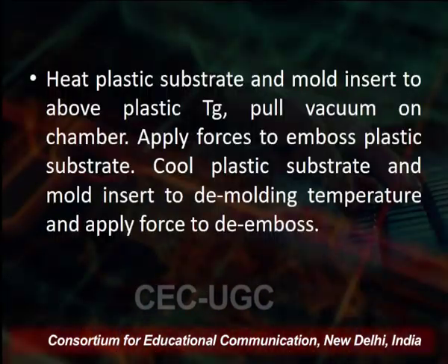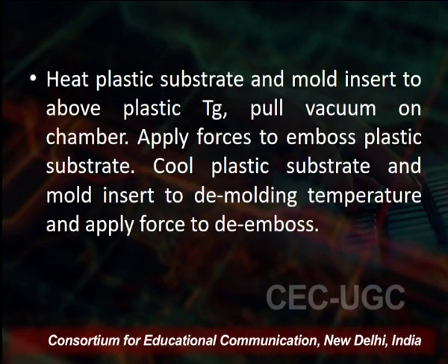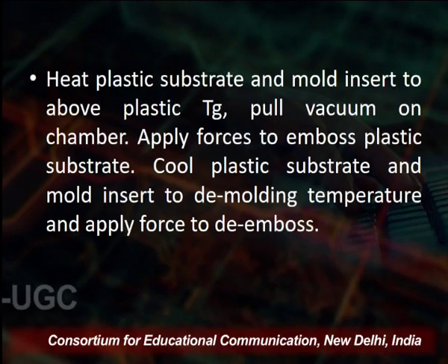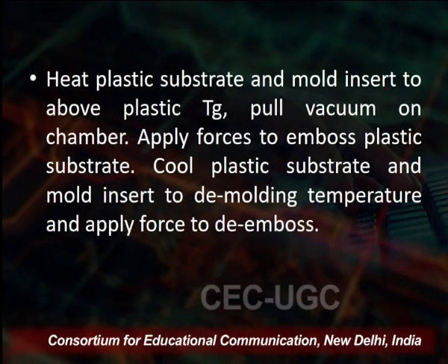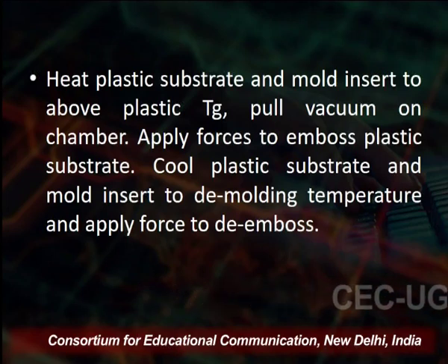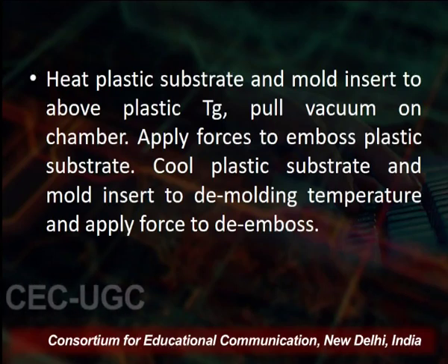Heat the plastic substrate and the mold insert to above the plastic temperature, pull vacuum on the chamber, applying the force to emboss the plastic substrate, cool the plastic substrate and then the mold insert to demolding temperature and apply force to de-emboss. This is a very simple process and that will be used.